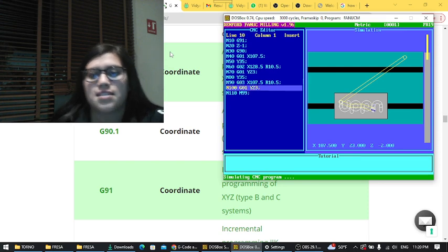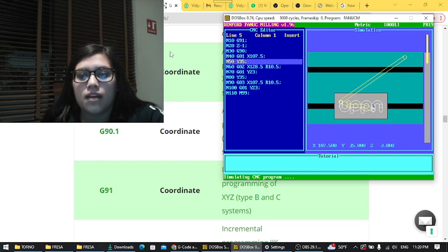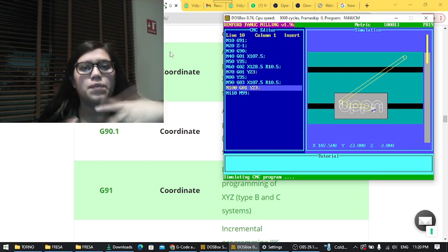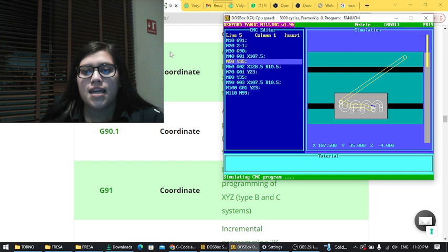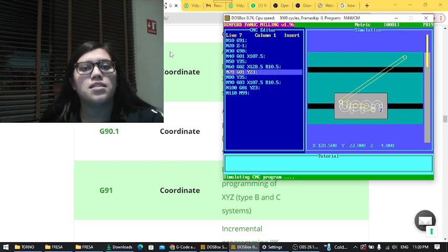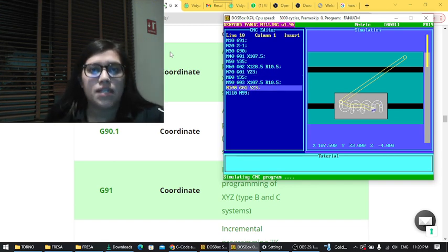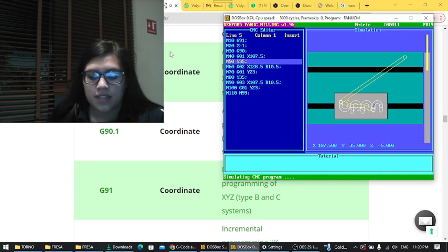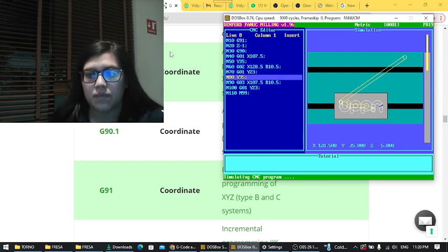So we're going to wait for the 10 cycles. After that, there's going to be a really fast process for the contours. The contours basically is just giving the letters a squared finish, because once we make the letters, because of the circle movements of the milling, they actually end up rounding, but this piece is telling us that we wanted it squared. Now, it also stated that it had 1 millimeter of diameter of, let's say, a preference, right? So we don't want one more and we don't want one less.